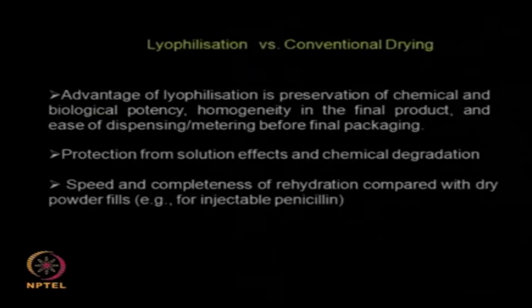So what are the advantages of lyophilization over conventional drying? Conventional drying I have been talking about before, where you apply vacuum, you apply temperature, so the water vapor evaporates and goes, whereas in lyophilization or freeze drying you freeze it so that the water becomes ice, and then you keep the temperature and pressure so that it does not go through the water phase, but directly goes into the vapor phase. So you are operating below the critical point.